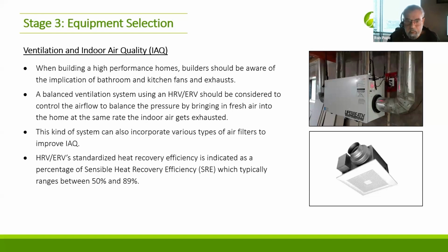I think it's insane to think about building a house these days without an HRV or ERV, right? There are other compliance paths you're allowed to use, but they're unbalanced. It's ridiculous to even have them available as a compliance path, and I think that's not going to last much longer, so I don't want to spend any time on those paths. You need an HRV, simple as that, or an ERV. Either one will do, and that balances the airflow and recovers the heat. And it keeps the house breathable, fresh, and prevents it from getting stale.